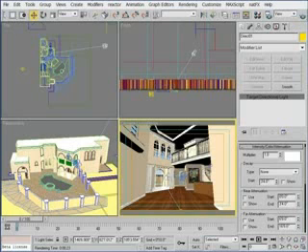And it still probably wouldn't look as good as if I just used fill lights inside the window openings. I do intend to use a lot of artificial interior lights, and that'll certainly combat the effect of splotchiness, but even with plenty of interior lights, I want to use fill lights for all the window and door openings. And I want to place the fill lights in these openings before adding interior lights because I want to get the natural light as realistic on the interior before adding artificial lights.